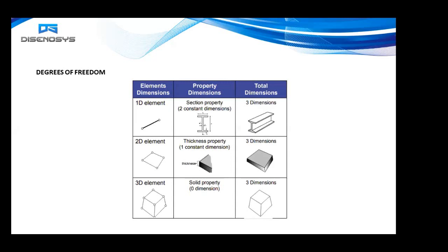If I model with solids, the number of nodes will increase, into degrees of freedom. So your computation time will be more when you model using solid elements. That is why we are not modeling with solid elements. Clear, Arjun?